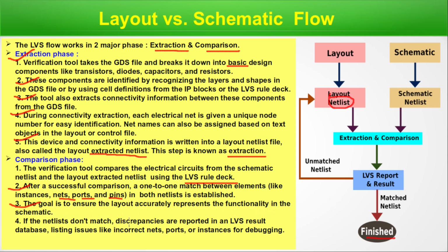If the netlists don't match, discrepancies are reported in an LVS result database, listing issues like incorrect nets, ports or instances for debugging. The verification tool prepares a net to net, port to port, pin to pin, one-on-one match between elements. If the netlists don't match, discrepancies are reported in the LVS result and we have to work on that. Like how many incorrect pins or ports or instances are reported, we have to debug based on that. So we are done with this slide.